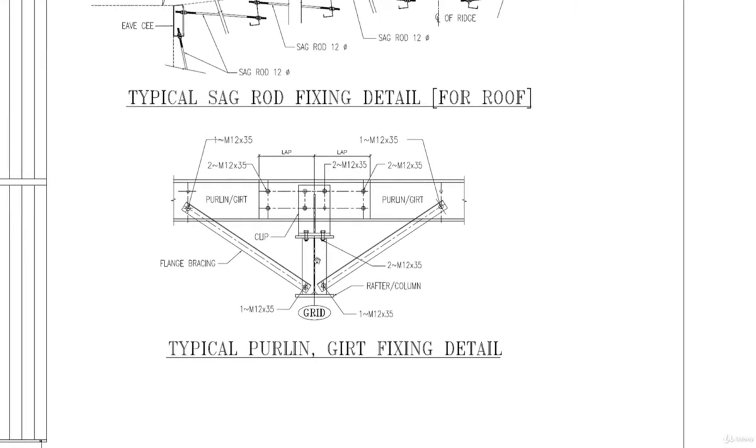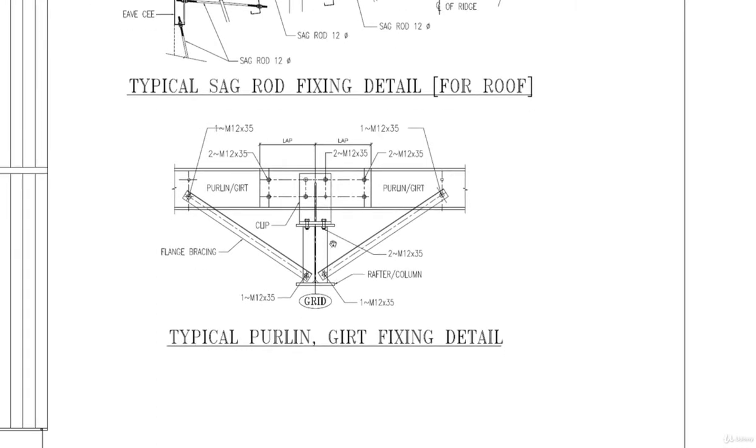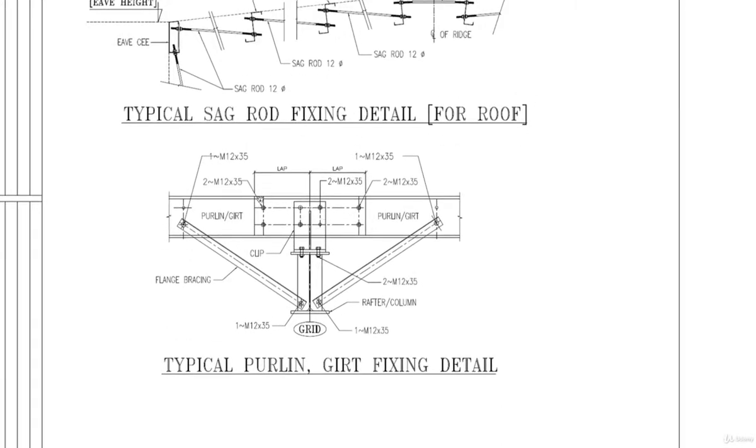sections. What we are basically achieving here is tying the top as well as the bottom flange of the section to the purlins. So here we have two advantages. Number one, the effective length of the purlin reduces, thus decreasing the size requirement of the purlin. Second, the bottom flange of the section is tied.